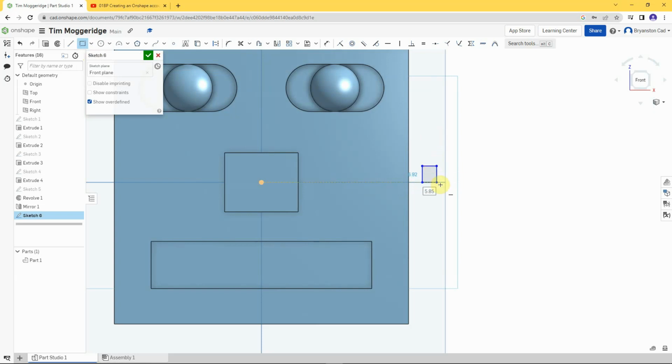I'm now going to left click on the bottom right of that rectangle and then draw another rectangle by left clicking. So I've got 2 rectangles drawn here. I'm now going to use the trim tool, and I'm going to trim away the edge twice where the two rectangles meet. So I've now got a kind of blocky backwards L shape, but I now need to dimension this.